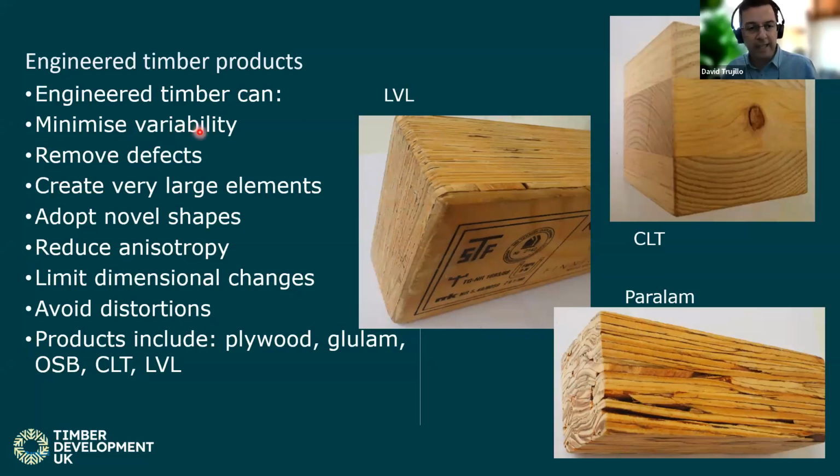Engineered timber is a really, really exciting field. There are many advantages. So we reduce variability, we remove defects, we can create very large elements, we can adopt novel shapes, we can reduce anisotropy, we can limit dimensional changes, we can avoid distortions. And so it is a field that revolutionizes what we can do with timber compared just to using sawn timber.